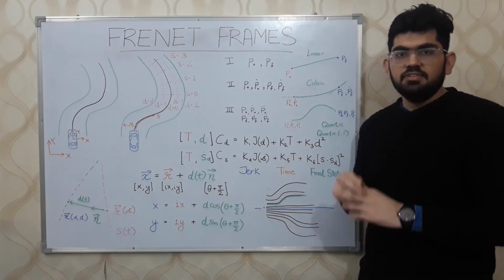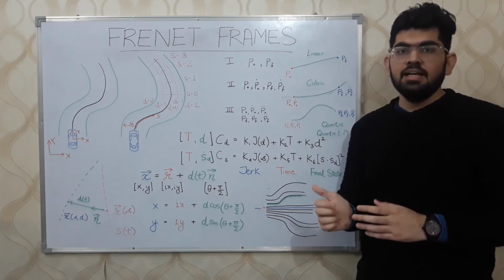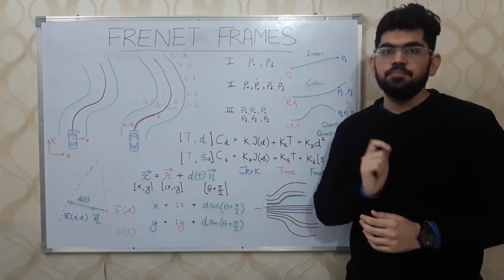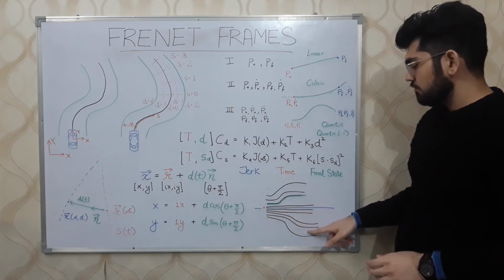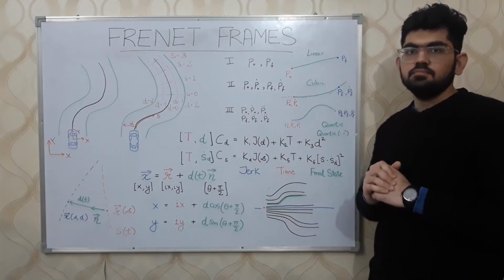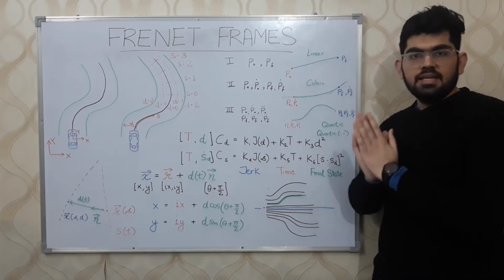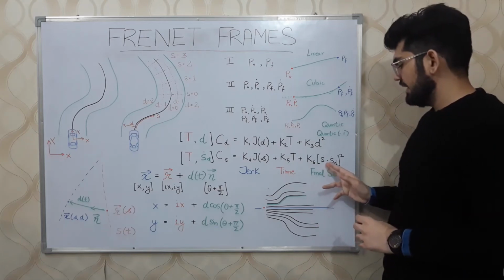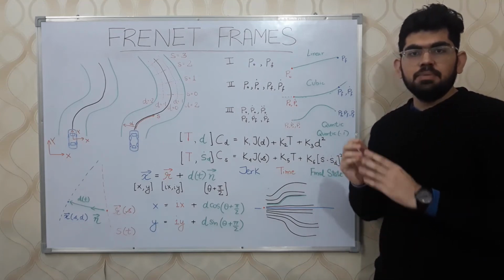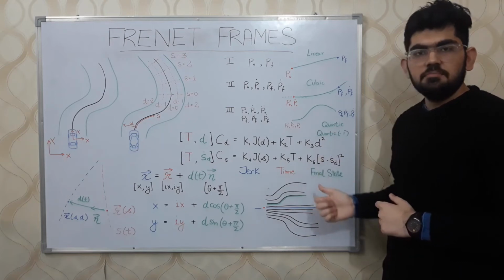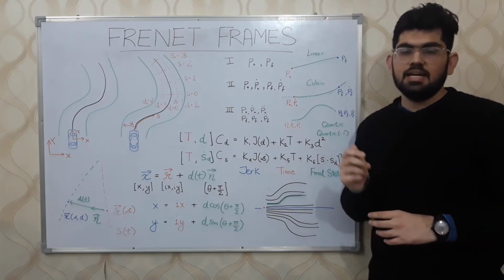For the d cost function, we have this final term d square over here. Our objective for the self-driving car is to follow the reference path completely. While we move on our road, we do not want our self-driving car to deviate much from this reference path. To minimize this deviation behavior, we have this d square term over here. In the s cost function, we have this (s dot minus s dot d) whole square term. Since we want our self-driving car to maintain the particular velocity that we have given, this term penalizes those trajectories that have speeds deviated from the actual commanded speed that we want.